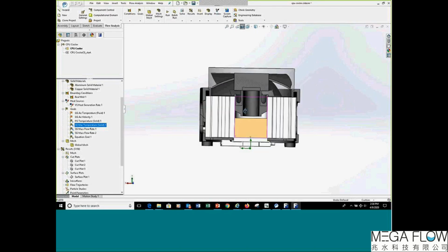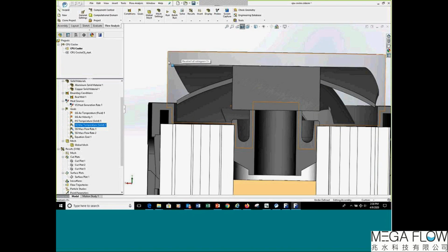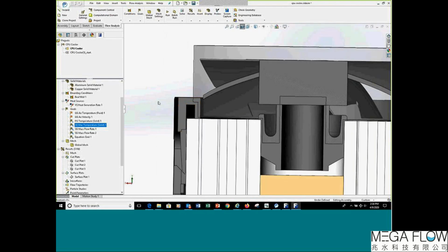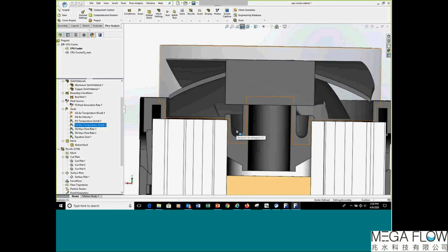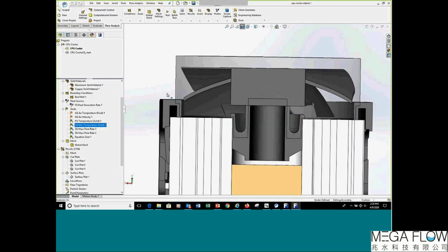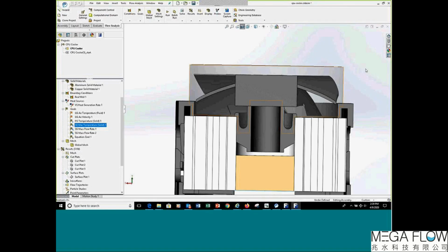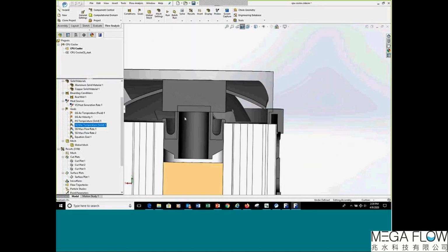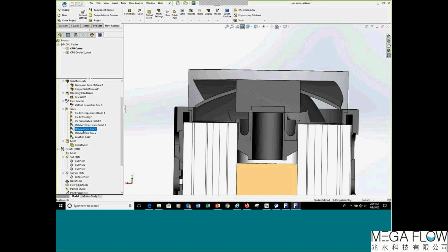So one of the things that they did with the shape of this, there was a reason for this, and I mentioned this before. They embedded the solid of that rotating region into the surrounding clip. And another reason why they did this, which you can do on your own in your own model, so that you can make use of this later, you'll notice something here. All of the flow that enters the fan has to go through the outer perimeter and the top surface. So all of the flow that enters the fan is limited by these two surfaces, okay? Because they end in the solid, it gives us a definitive break.